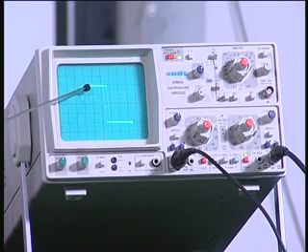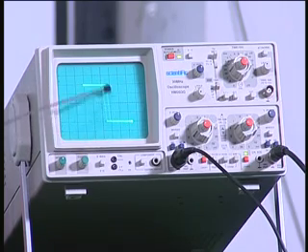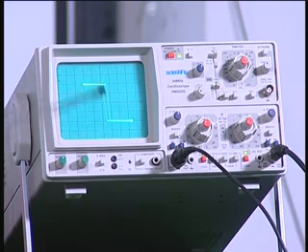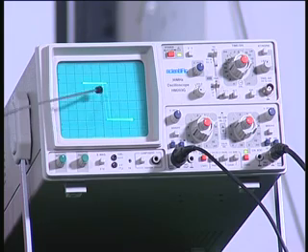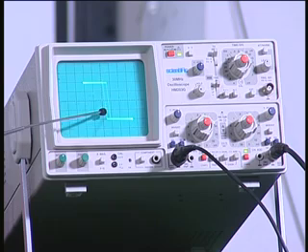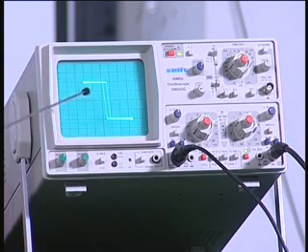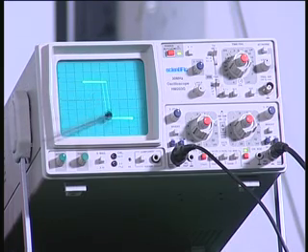So you have a saturation here and you have a saturation here, and you have the corresponding large slope. I did not mention to you that this is the linear portion of the amplifier, and if you calculate the slope of this vertical line, you would find that it gives the open loop gain of the amplifier. So this gives us a method of measuring the open loop gain also, and I don't know whether you were able to see that, if you come close and have a look at this, you can see there is saturation here, there is saturation here, there are 2 lines here.